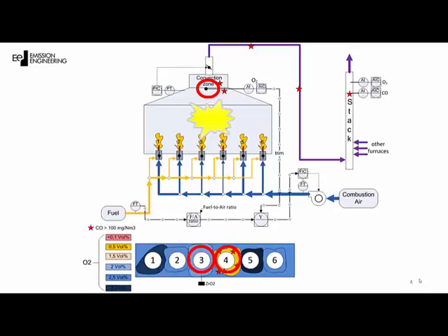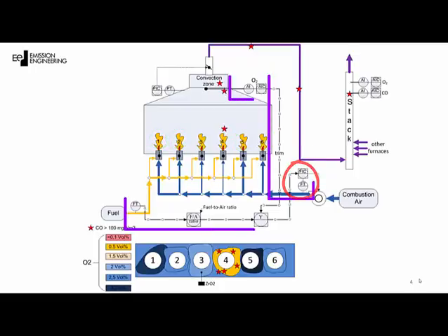This means that the burner air dampers of burners 3 and 4 are opened up, and the effect can be seen on the oxygen analyzer. But the conditions of burners 1, 2, 5, and 6 would remain unchanged because the total airflow rate is kept constant by a fuel-to-air ratio control loop in the DCS. Thus, the furnace is treated so that the oxygen analyzer conditions are satisfied, but this isn't necessarily the best for all burners.